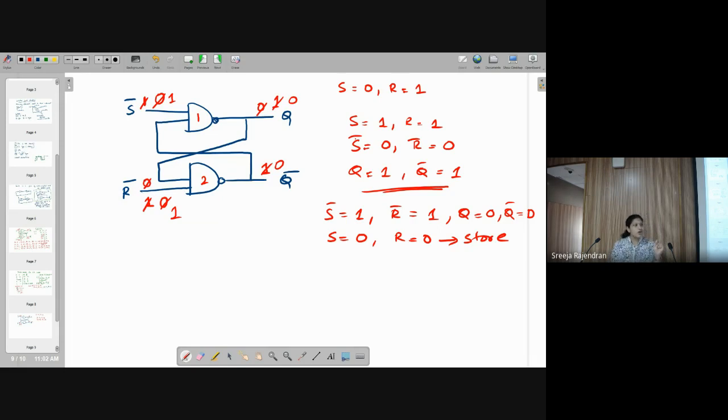There will be a small amount of difference in the NAND gates. So never will I be able to generate both outputs at the same time. Each gate will have very minute difference. It is not something that we can quantify as a large value, but there will always be a small difference.